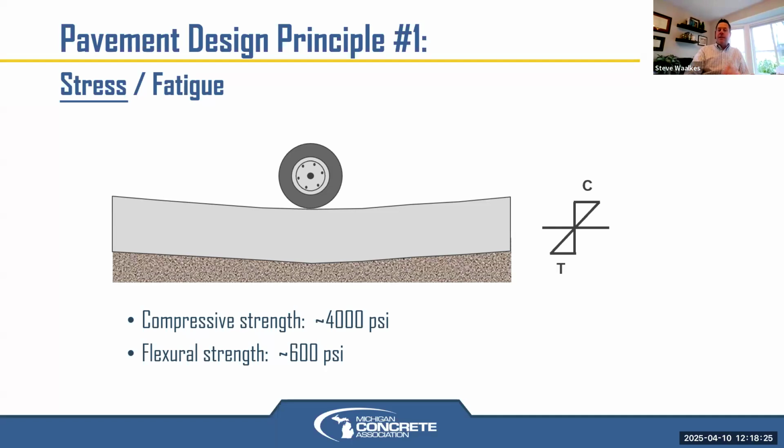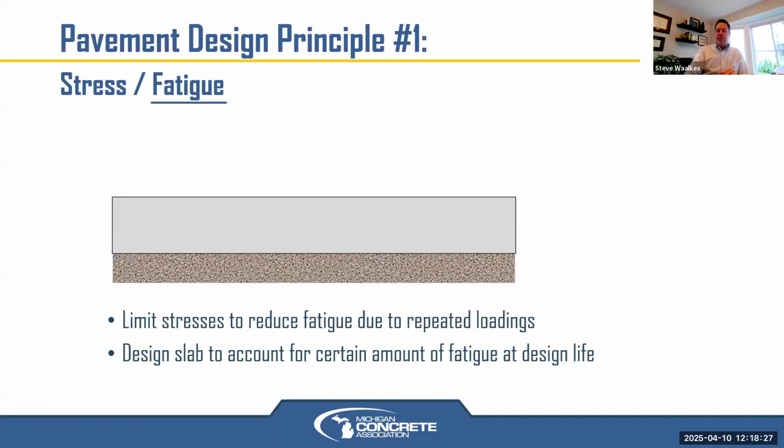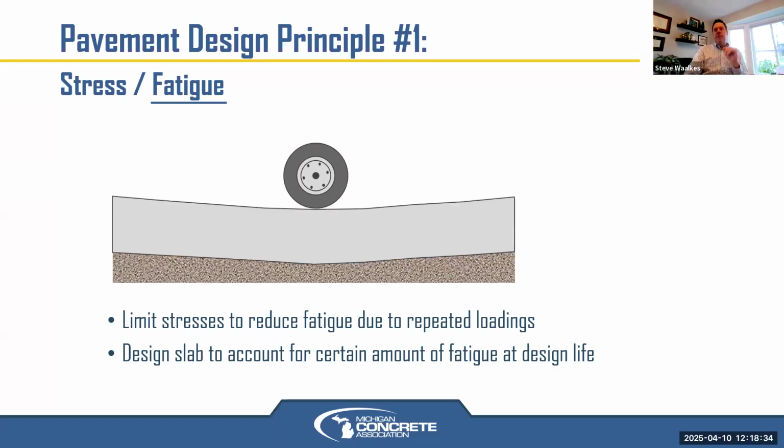But even if we don't exceed the strength of the material with that stress, over time, repeated loadings could lead to the fatigue principle, where if we're roughly between 50 to 90% of our strength with that ideal stress or maximum stress condition, it will eventually add up to the point where repeated loadings will cause a fatigue crack. So that's really the main principle we're designing for on the engineering stress side.